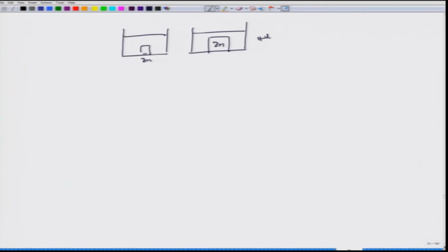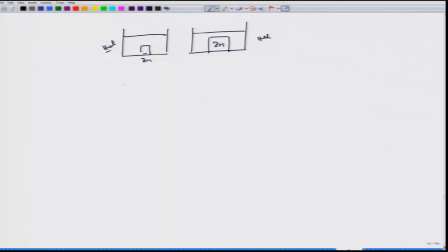Now, this is in HCl and this is also HCl. So, this is uniform mode of corrosion, but many a times, for example, in case of atmospheric corrosion of iron, we do not see that. If we start from 0 time and after spending certain days, you take out that particular metal piece without disturbing the surface conditions, that means you are carefully taking the sample without disturbing the surface and weighing the small item or the plate you have exposed to the environment, you might see that there is weight gain rather than weight loss. So, in certain cases we see that this is weight loss and it becomes straightforward.